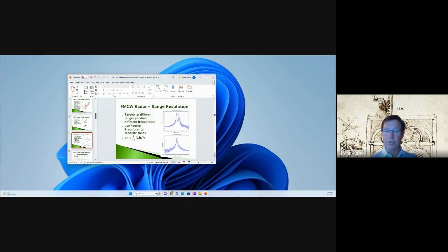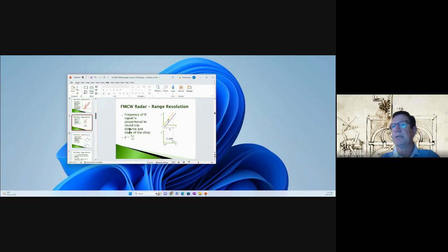So if you can observe the waveform for longer, you can get more information about its frequency components and drill down more precisely. So if we want delta F to be nice and small, then if delta F was a little bit smaller, maybe we could resolve those peaks in this second case, but they're just too closely spaced right now. And so if we want that to be smaller, we want TC to be larger. So larger TC then will give us